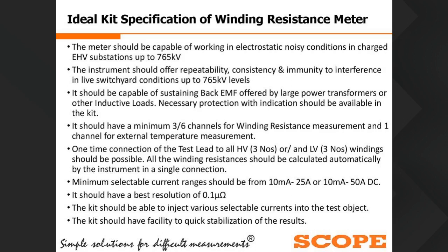To reduce the time, I recommend users select 6 winding resistance measurement channels, so the user can measure the resistance of 6 windings simultaneously in a one-time connection.